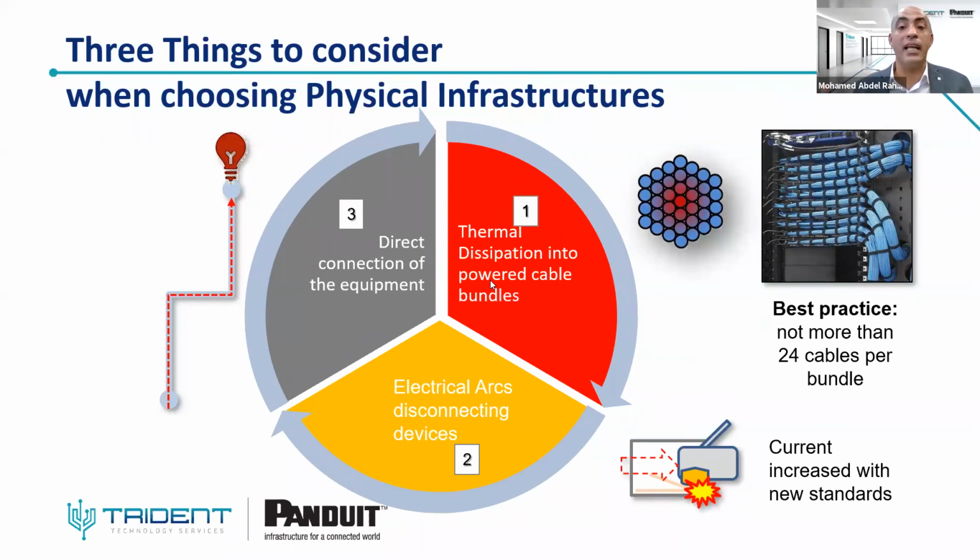You need to consider another factor, the temperature rating. You need to choose a cable with a higher temperature rating. Also, as per recommendations, Cat6A cable, and if you can have a wrapped cable or wrapped foil for the cable, it will be good to use in your solutions, like matrix cable.